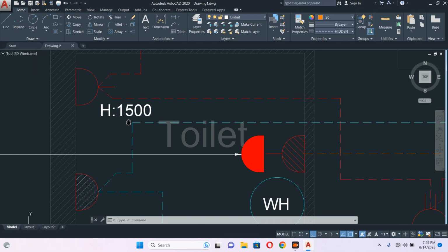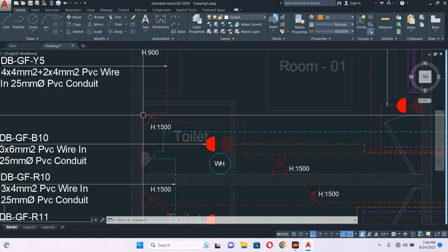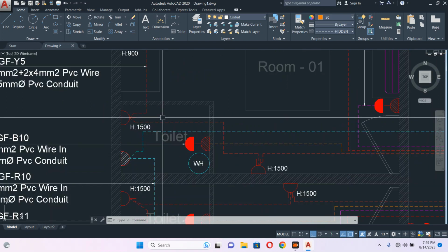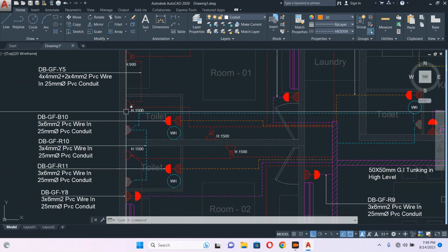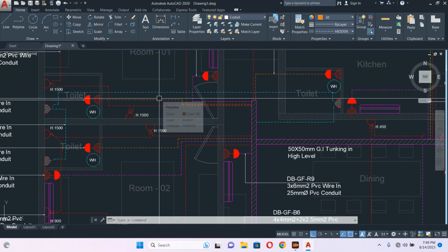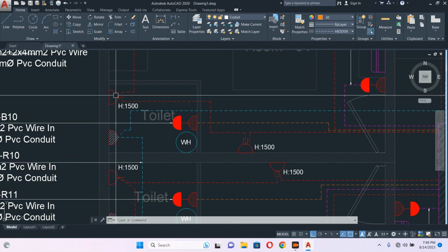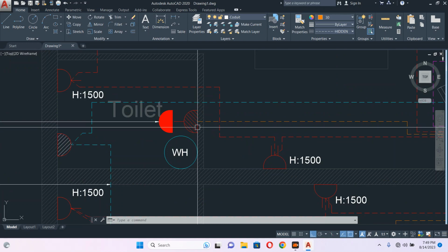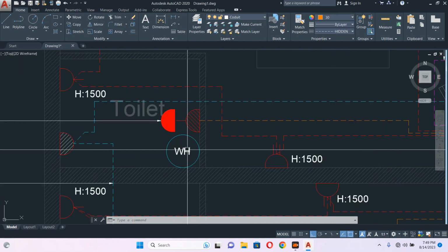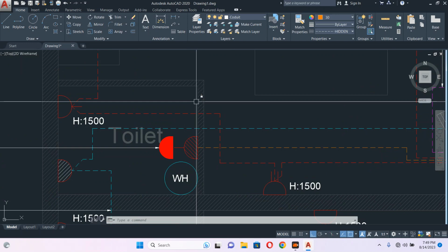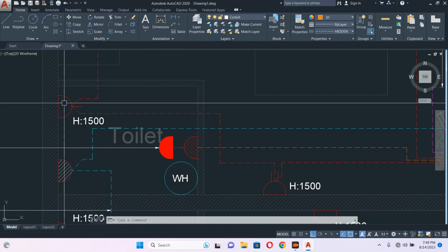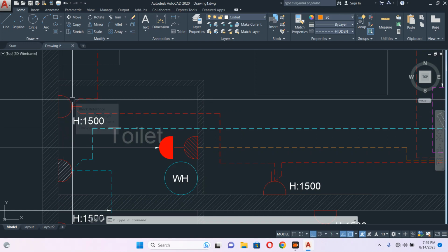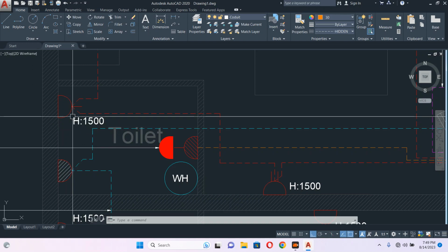This one is the saver outlet, I told you. Yes, I remember this one. Generally it will come on a separate supply, but here I have connected it, so no problem. Some consultants make a separate outlet. So see in the toilet: saver outlet, sensing outlet, sensor for the spare outlet, and DP switch with flex outlet for the water heater. It can be another one for the hand dryer, and beside this switch socket, saver socket, you can put another socket, because the saver socket looks different, not like a regular socket.